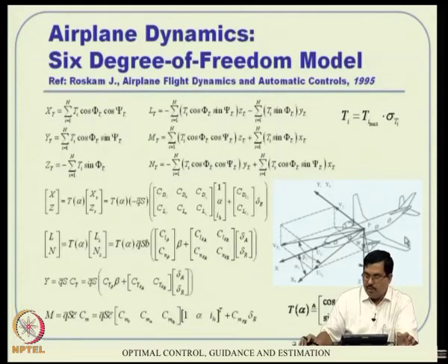as seen in the body frame. With respect to the body frame, these engines are typically oriented by angles phi and psi for certain beneficial properties. I will not talk too much on that. One thing you can visualize is that if it contributes something in the inertial vertical direction, then it helps the lift sustain the weight. So you don't really have to have a very big wing to sustain your lift.